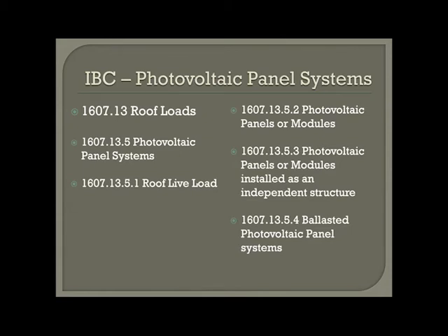As far as installation issues, other than that, would be overspanned rafters. You will address that with plan review when you're getting your permit. There you could either take the option of getting engineering or show them how you're going to add or sister onto the rafters to bring them up to span. Let's see what else I've got on here.